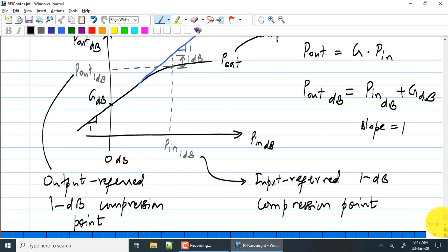Now, at Psat, the output is literally clipping. If you move back a little bit, output has not started clipping, but it started distorting, right? You don't have the gain as before. Make sense? So you are already at the point where the output is swinging quite a bit, very close to clipping. So P1 dB is not good enough for us. Majority of time in the receiver, you are not going to be anywhere close to compression. Second problem. You have a second problem.